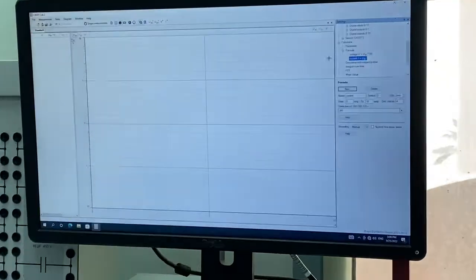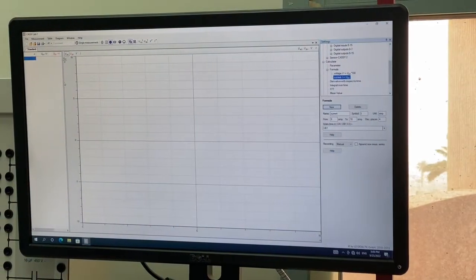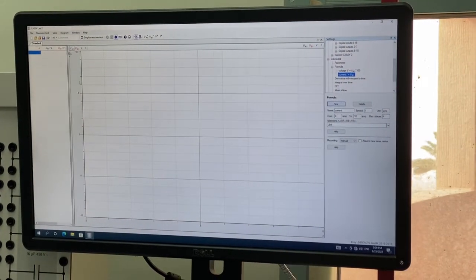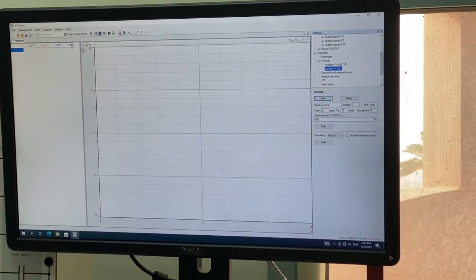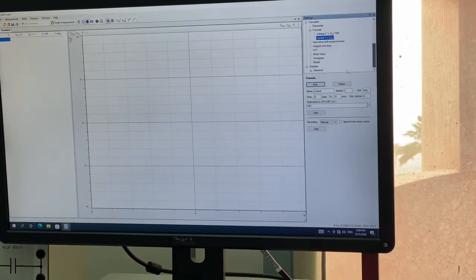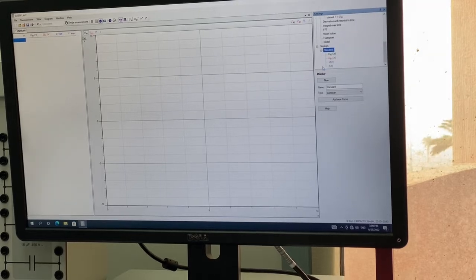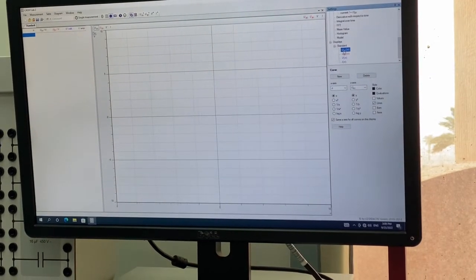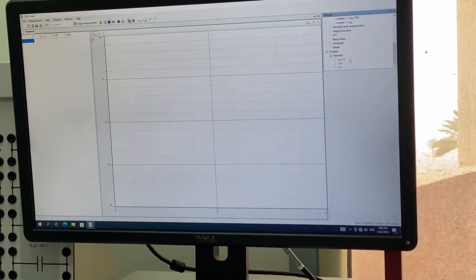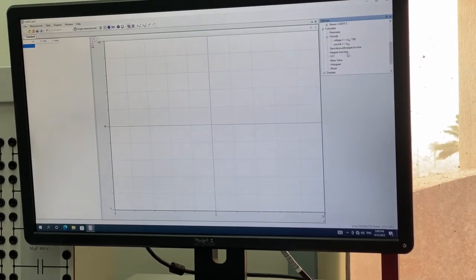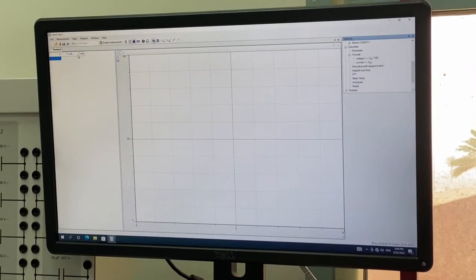So done. These two things we have already got. You can see over here it appeared, voltage and current. So you go to the display, standard displays. They already have UA1, you don't want to see it, you just delete. UB1, you just delete. So the two things you have here, voltage and current, you see?